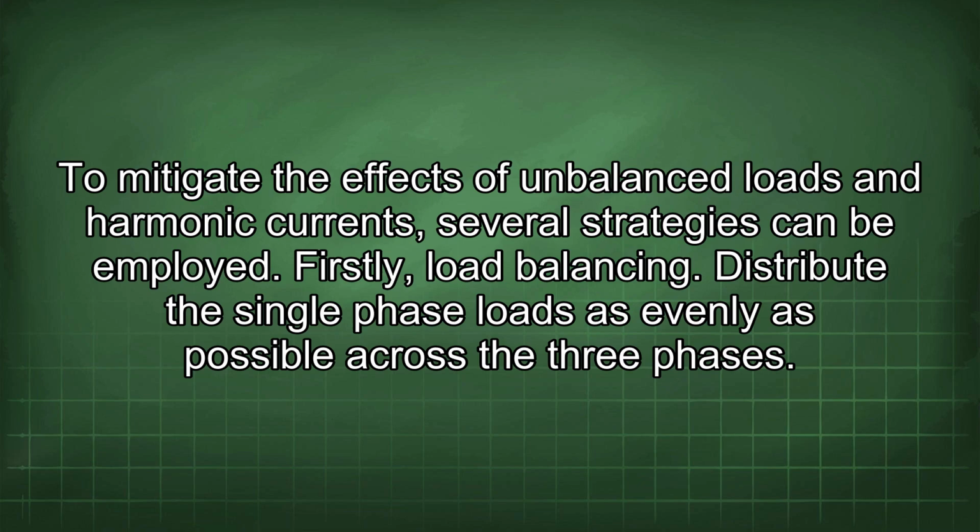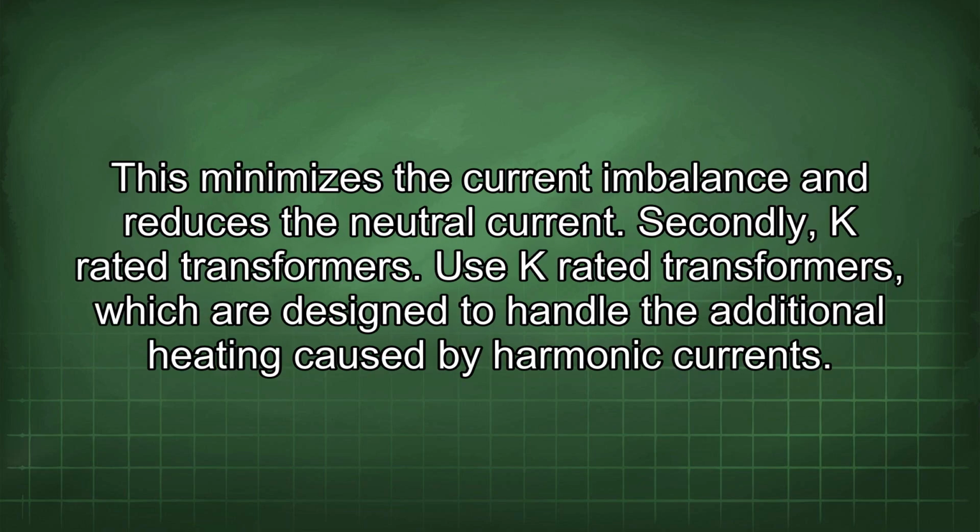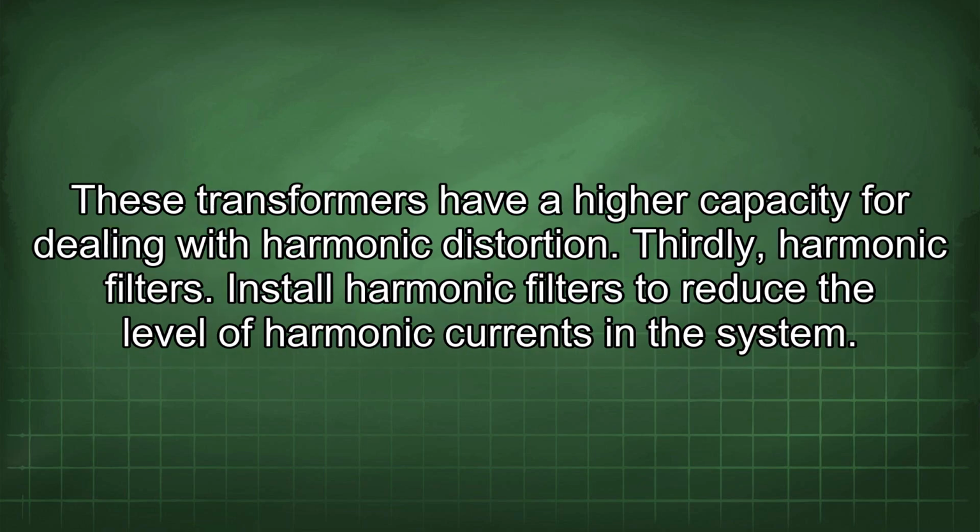Firstly, load balancing. Distribute the single-phase loads as evenly as possible across the three phases. This minimizes the current imbalance and reduces the neutral current. Secondly, K-rated transformers. Use K-rated transformers, which are designed to handle the additional heating caused by harmonic currents. These transformers have a high capacity for dealing with harmonic distortion.